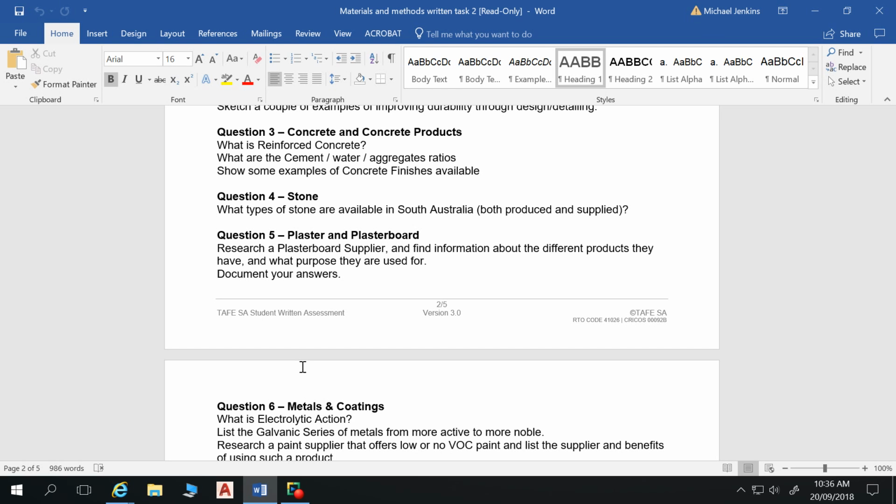I was curious about what sort of cement, because it wouldn't be the same, I would have thought, as the flooring cement. It'd have to be different. I don't know. So you'd want a decent amount of workability in that concrete, because you've got to get it in a 90 mil cavity or so. Okay, so there's a fair bit of space in there.